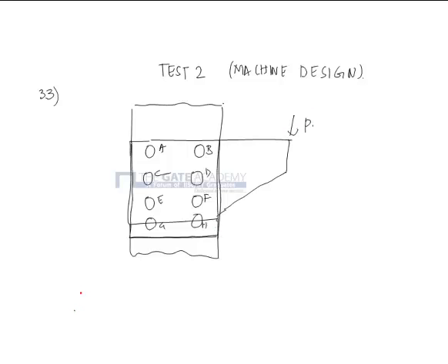What is asked is which rivets will have more stress. So it basically boils down to finding out which rivets carry more load, because that rivet only will have more stress.